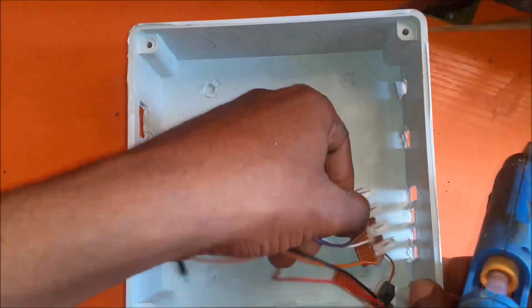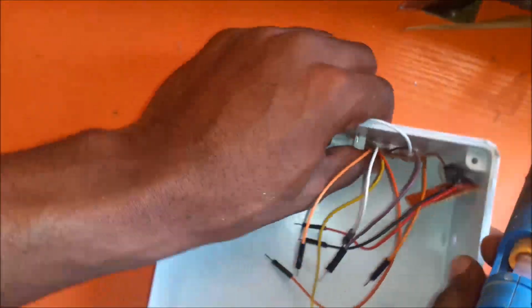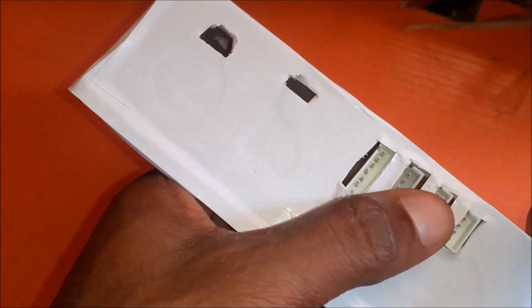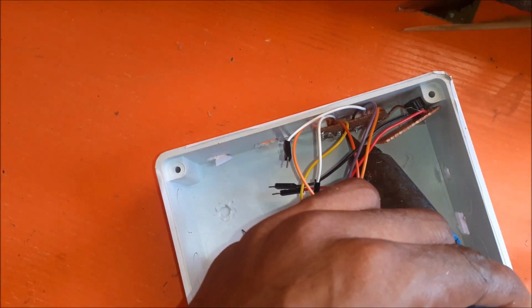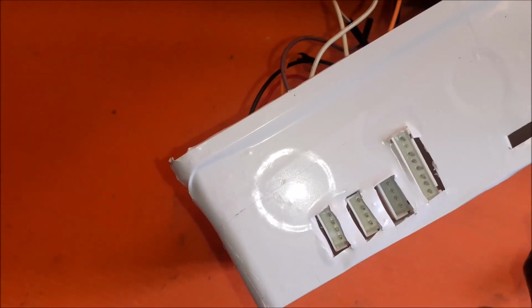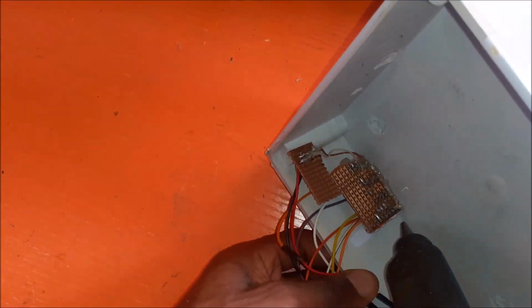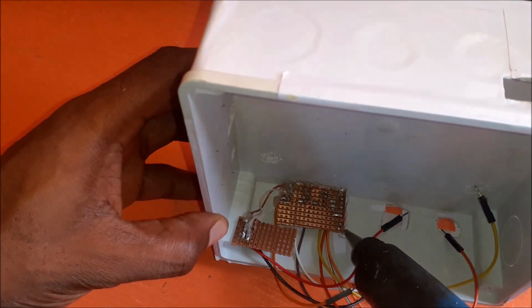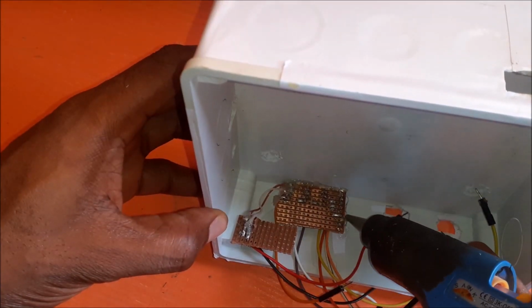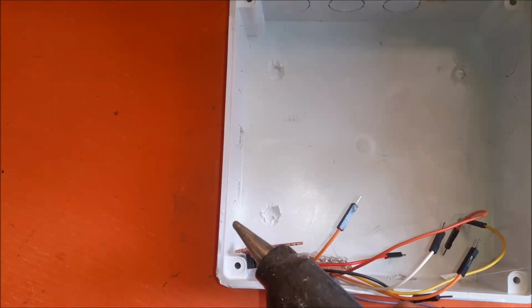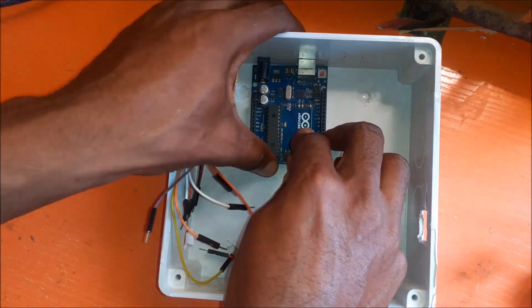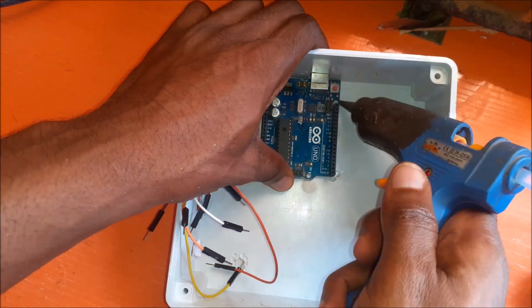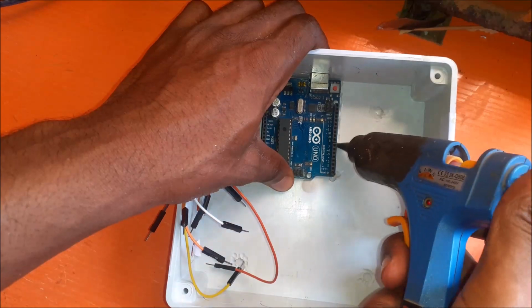The next thing would be to glue the connectors that we will use to connect the sensors to the development board, since the schematic diagram specified that we used an Arduino Uno board and a NodeMCU development board. These 2mm JST male connectors will house the female wire connector when we connect the sensors from outside the project enclosure design. These male connectors are soldered onto a Veroboard, to which we in turn solder a male jumper wire, so as to enable us to connect it to the Arduino development board itself. The whole process is for ease and convenience of the wiring and connection as specified by the circuit diagram.